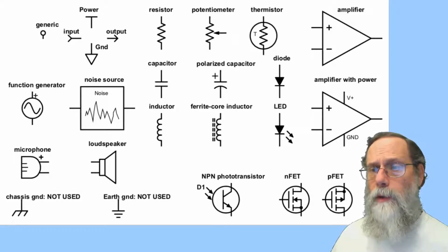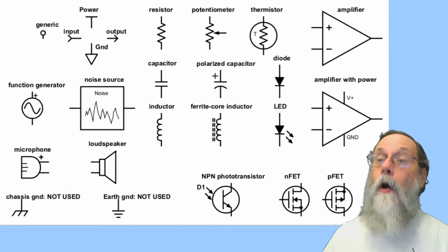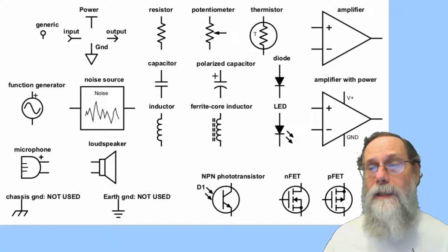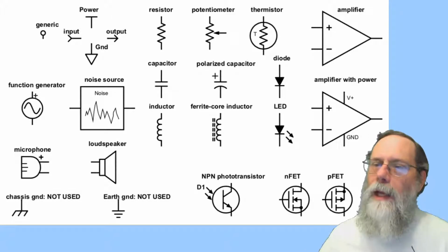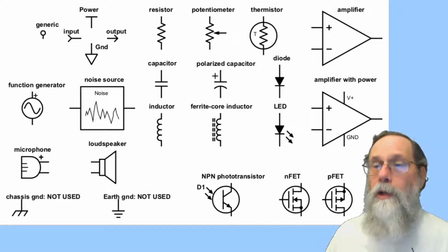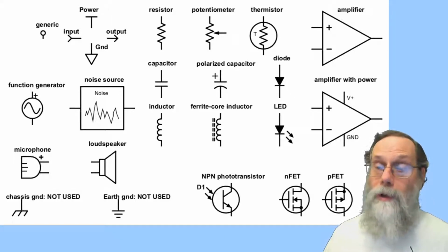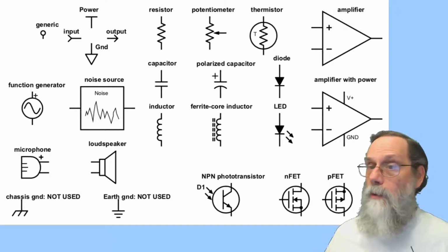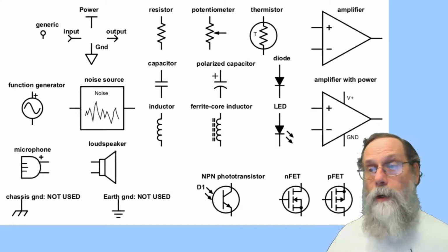Remember, the ports are what we use for the schematic to communicate with the outside world, the stuff outside this schematic. And that's not necessarily the outside world in the sense that you might think for a sensor system. It's the stuff that's outside this particular drawing. So if we have a schematic that corresponds to 1 block of our block diagram, well, the blocks it's connected to at the input and the output, those are outside. So we need to have ports to connect from the schematic for this block diagram to the schematics for other block diagrams. And that's what the symbols in the upper left corner here are used for.